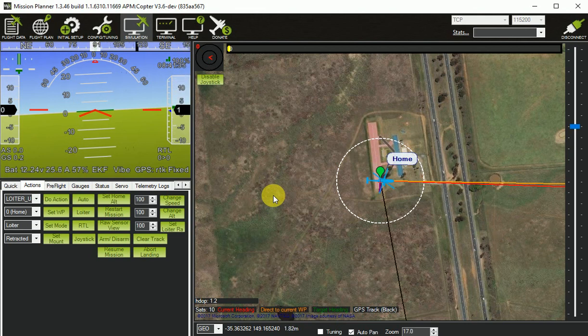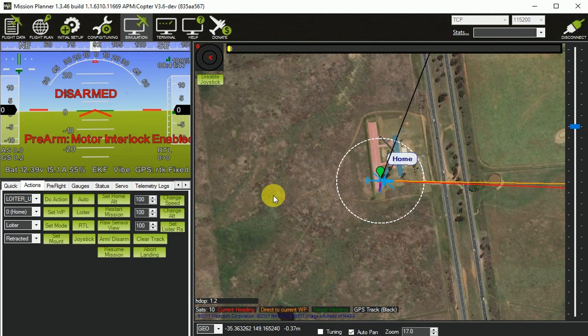One that I quite like using is a Taranis transmitter. Just use the USB port on the back of the Taranis, and the Taranis acts as a USB transmitter when you connect the USB cable to the back of the transmitter, and that allows you to use a full RC transmitter with software in the loop simulation.